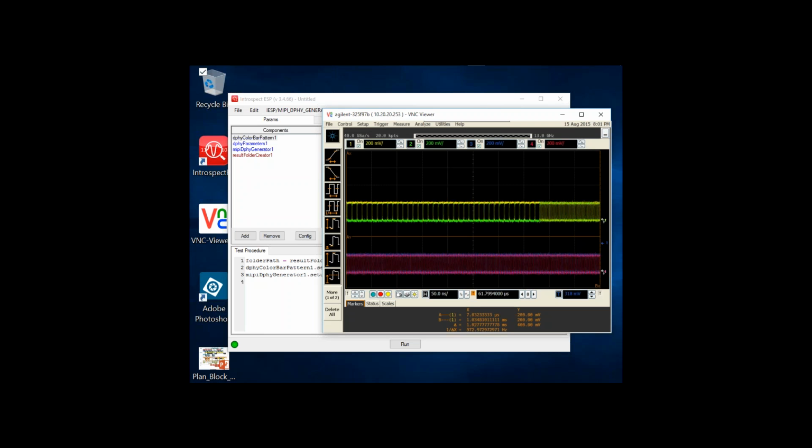If we zoom into other sections of the pattern, like towards the end of the packet here, you'll see that it's the opposite now. It's a single positive 1, so the positive lane is all zeros and a positive 1. So it's a 1 in a sea of zeros, and again, that's the complement of the previous test, showing the ability of the receiver to detect a single lone pulse in a sea of zeros.